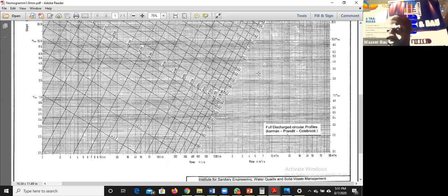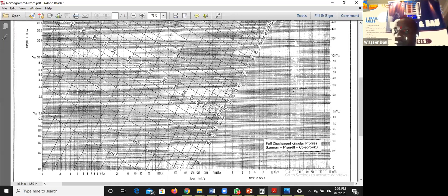So the limitation of this chart is that for any discharge that requires a drain size of more than 1.2 m, this chart might not be strictly applicable. It means you need to combine it, or you need to do some level of iteration to get the value. Okay?